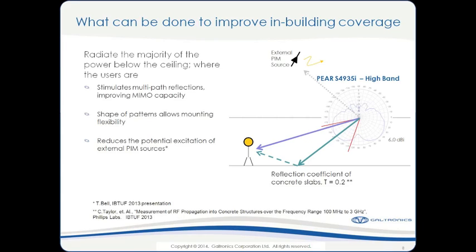For some reason, municipalities and zoning laws are concerned about antennas more than they are just the electronic boxes. So you don't want to be having to go back and replacing the antennas later. So what that means is, install multi-band broadband antennas from the get-go, from day one, so that you don't have to reapply for permitting and licenses down the road.